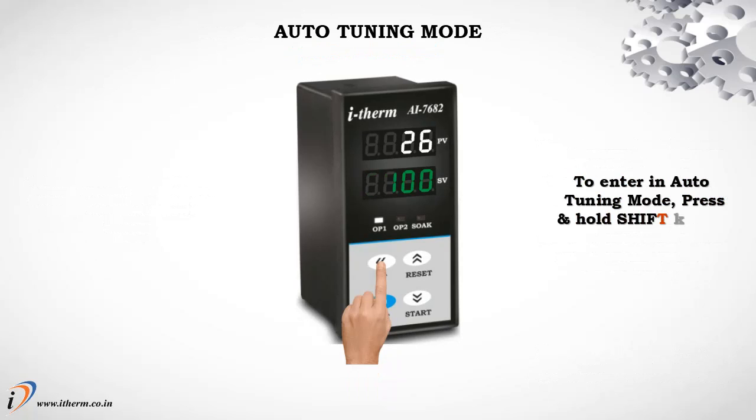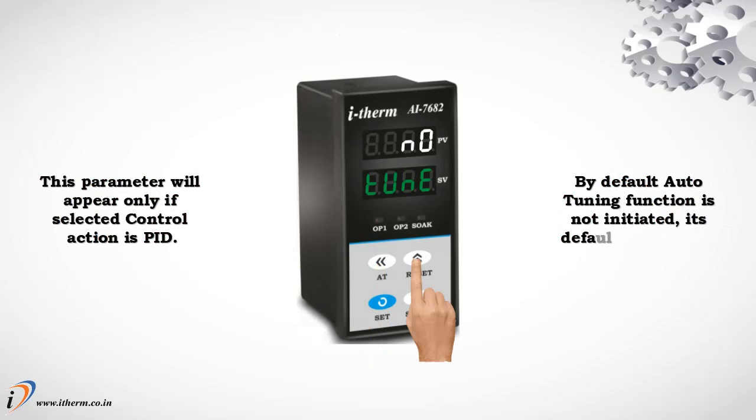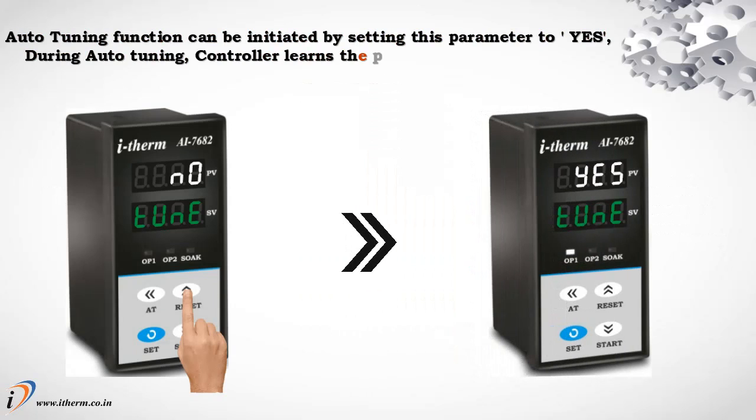Auto-tuning mode. To enter in auto-tuning mode, press and hold Shift key for minimum 3 seconds. This parameter will appear only if selected control action is PID. By default, auto-tuning function is not initiated. Its default value is no. Auto-tuning function can be initiated by setting this parameter to yes.